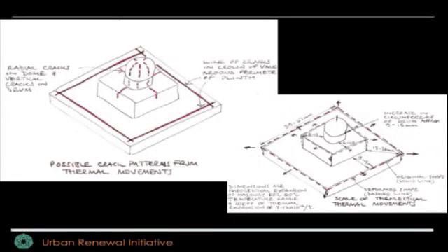What do we learn from this? We learn that these cracks have been caused by thermal expansion, and it would be best for the building not to fill up these cracks, not to repair these cracks. Now, as a conservation architect, my first instinct is: a crack, let's stitch it up.